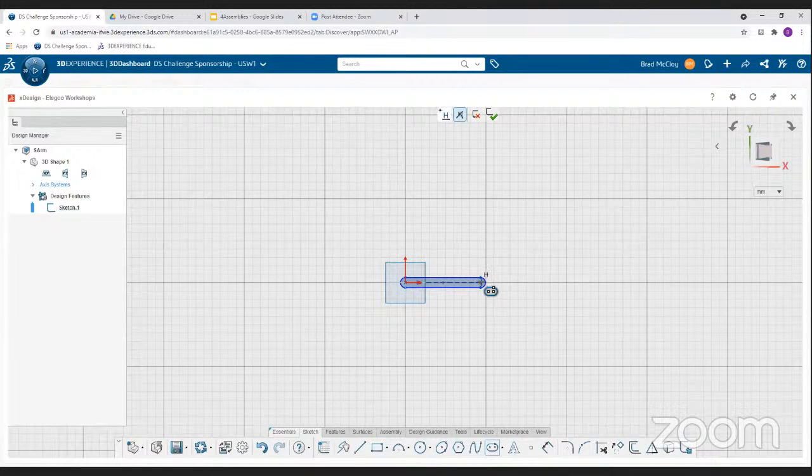If I drag it and move around, I'm going to hover so I get the H, which means this will be horizontal. So it'll be defined horizontal. And now I've defined the length of it, and I can give it a thickness too. So you can see that's a pretty cool feature where we automatically get this closed circular shape. Often for a slot, say if you had a screw you're going to put in, you want the screw to be able to slide back and forth in the slot. That's what it's useful for.